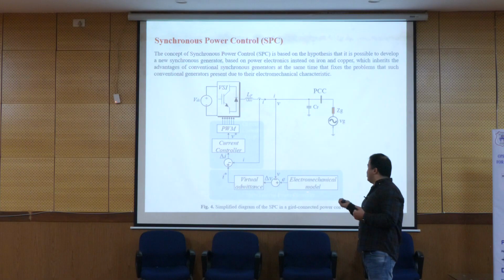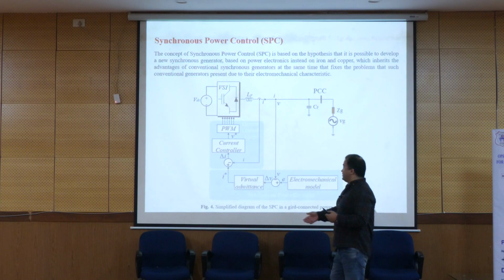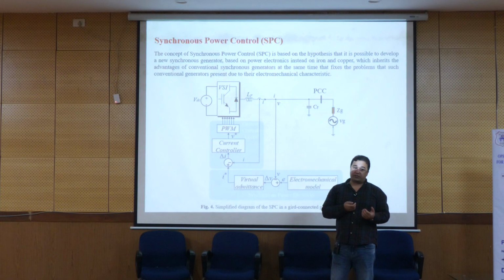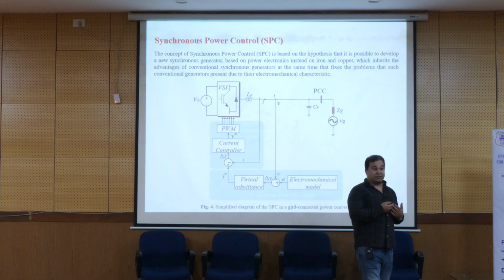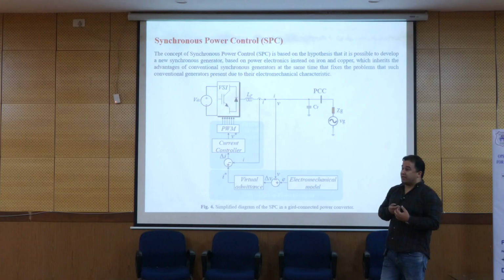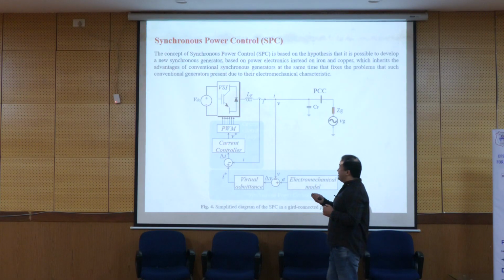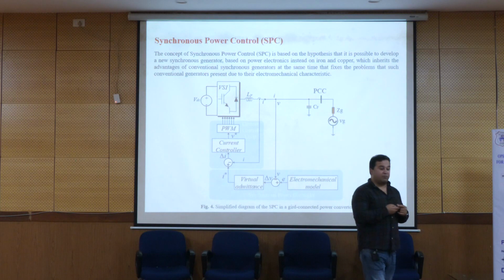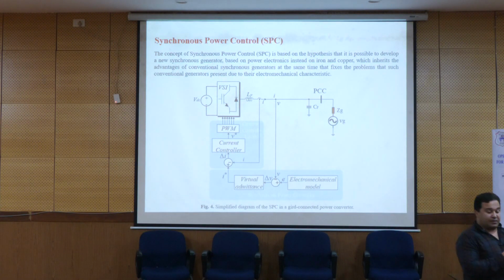So what we do here is that we provide the virtual admittance. The injected current we consider as a reference from the converter to the grid is somehow less polluted by high frequency pollution, and by this we can ask the current controller to provide the power with higher quality.